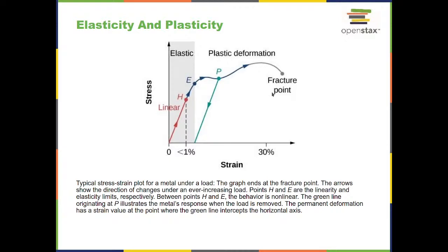At some point we're going to get, of course, fracture, or the object will break. In particular, if we do tensile measurements, then it will just break in half. If we do compressive stresses, then the object will likely break by buckling instead of breaking in two pieces.